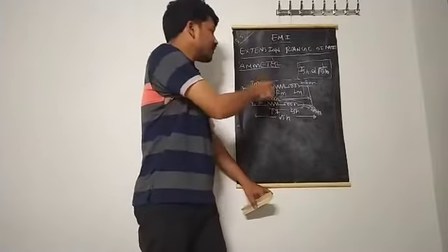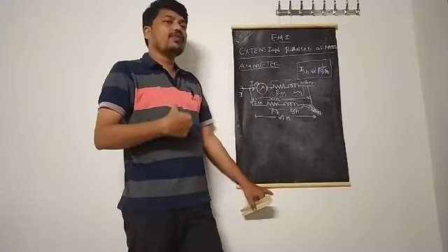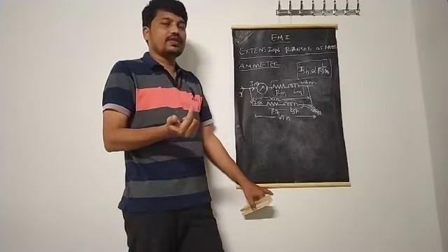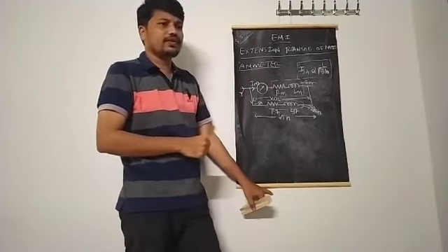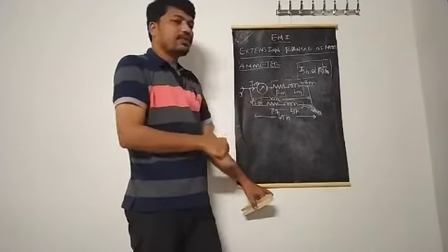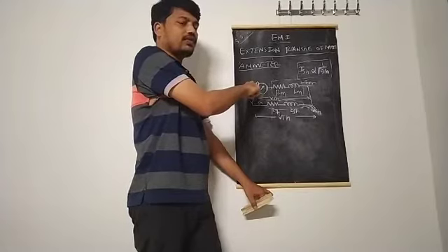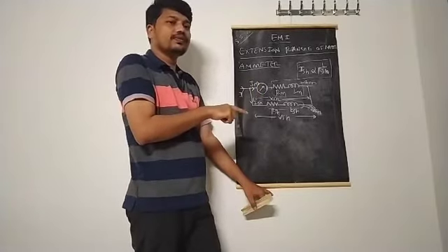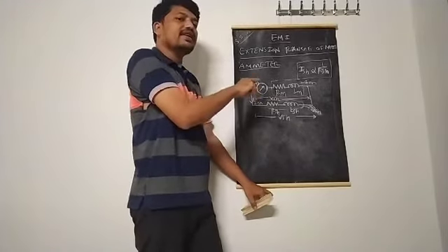This existing meter carries only the meter current IM. Suppose, for example, we want to extend the range by increasing the current. Say IM carries 2 milliamps, the maximum range of this meter. But I want to measure 2 amps. Is it possible to measure 2 amps? Not possible, because the 2 milliamp meter cannot measure a 2 amp current.